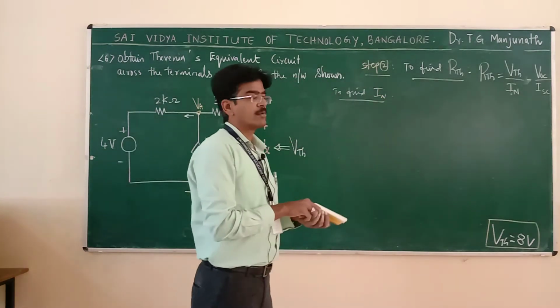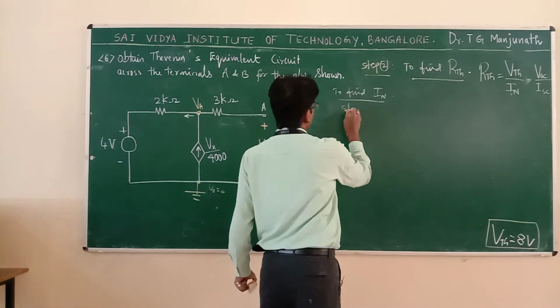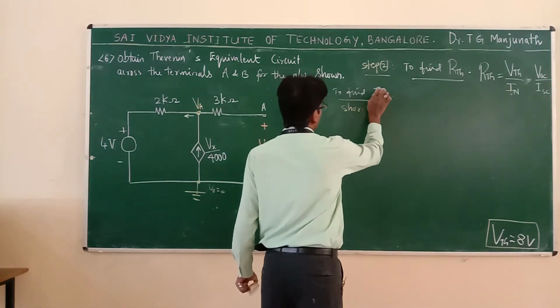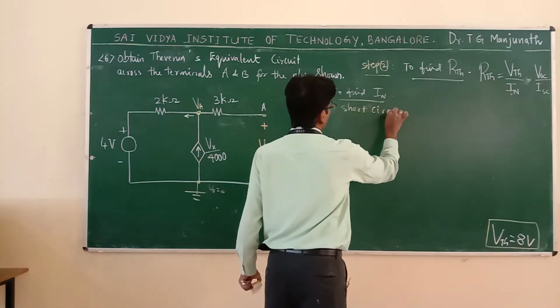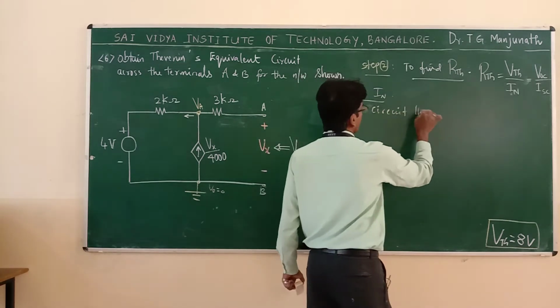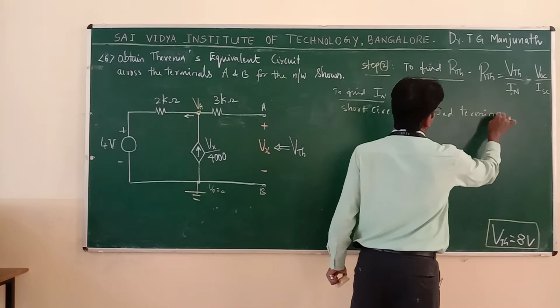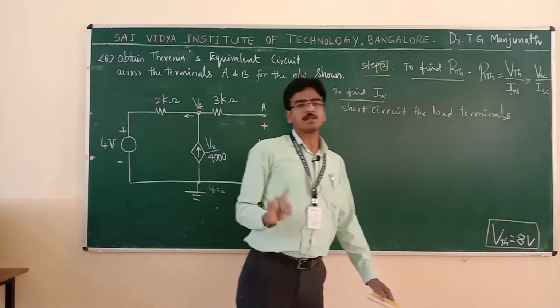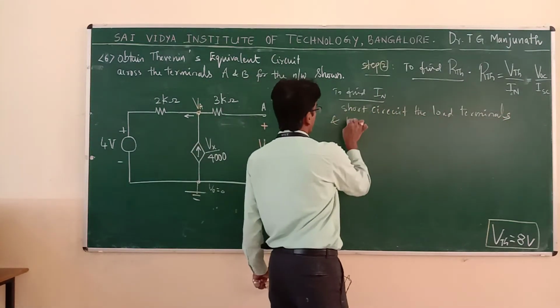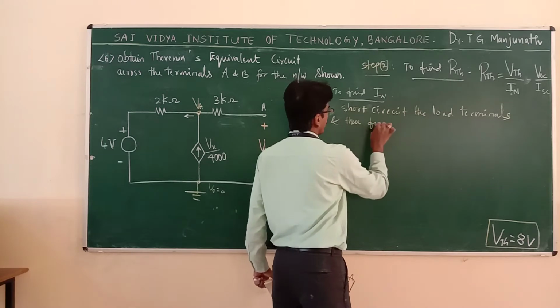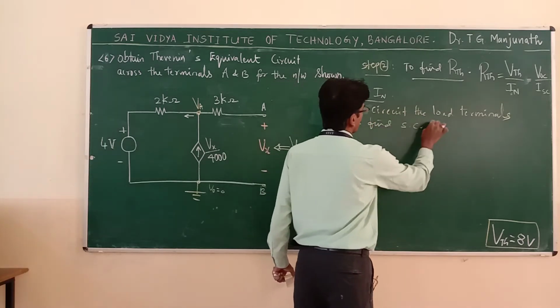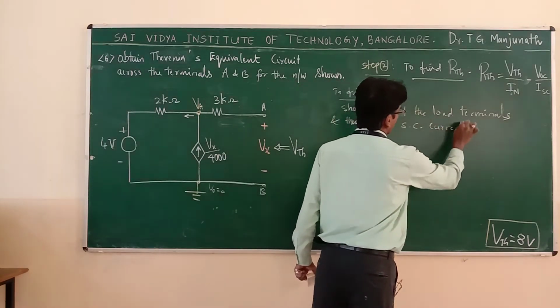To find IN, short circuit the load terminals first and then find the short circuit current.